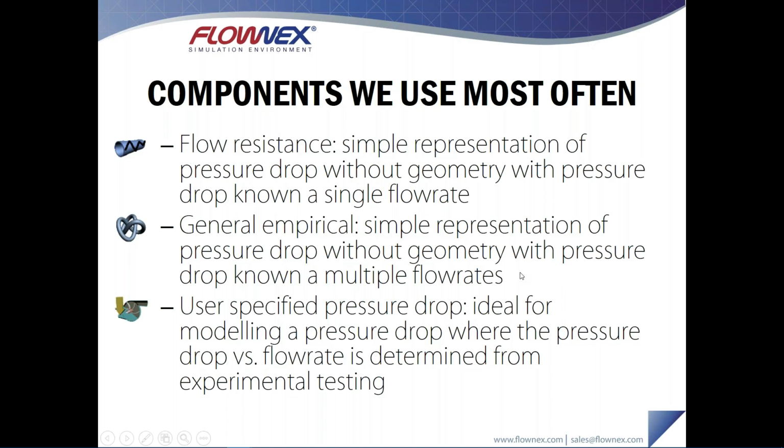So we can vary a coefficient similar to a secondary loss coefficient to scale the pressure drop, but then also vary the exponents for density and volumetric flow to account for how the pressure drop varies with these variables. What I often use is a small spreadsheet that I've built that does the regression calculation for this.